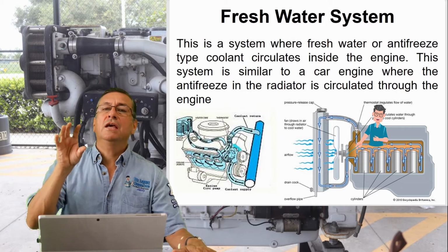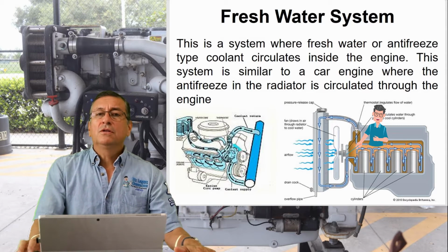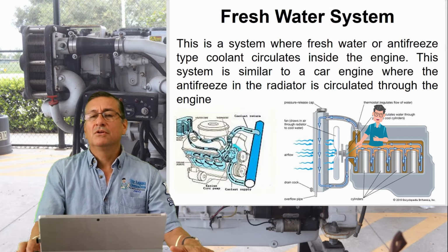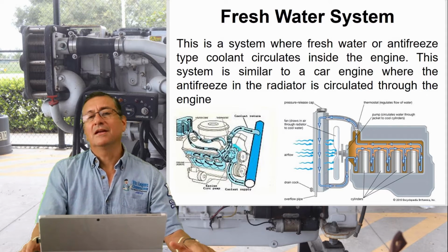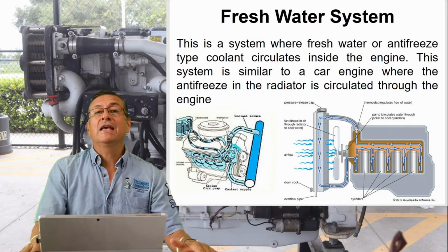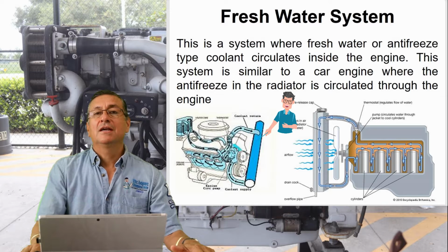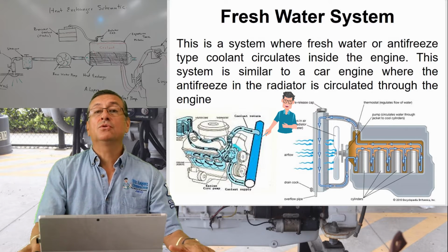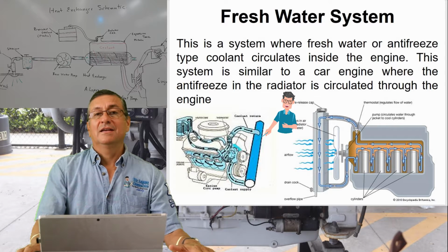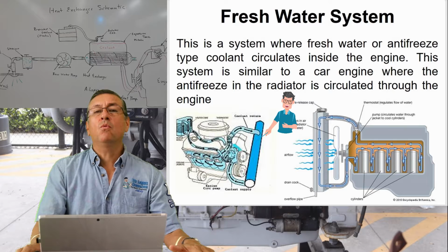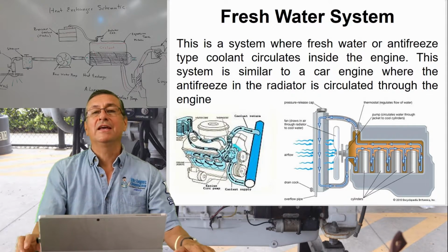This is the engine in your car. In your boat, it's pretty simple. You only replace the radiator with a heat exchanger. Now the coolant passes through the heat exchanger internally. You see the serpentine is the same, but in the heat exchanger you have salt water. The salt water passes through the heat exchanger, goes out the other side, enters the exhaust manifold of the engine, and bye-bye.